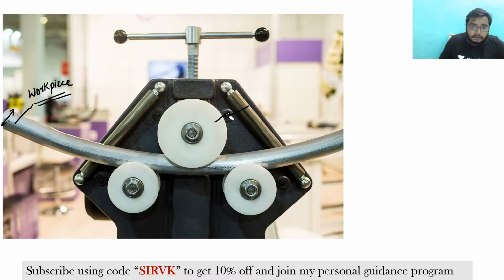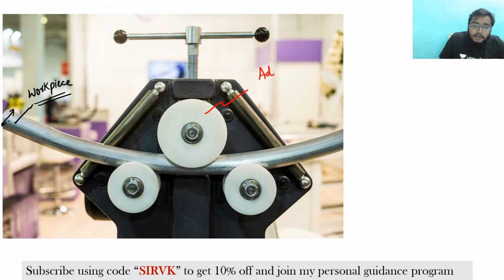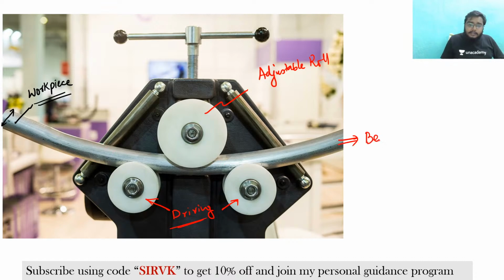Just let me change the color. So this is the adjustable roll. Fine. So what is the use of this adjustable roll? Based upon the thickness, this roll will adjust that. You can loosen it, and you can adjust your workpiece based upon the thickness of the workpiece. These two are the driving rolls, and these are rotating, and hence you are getting your workpiece to be bended, and hence bending is done.